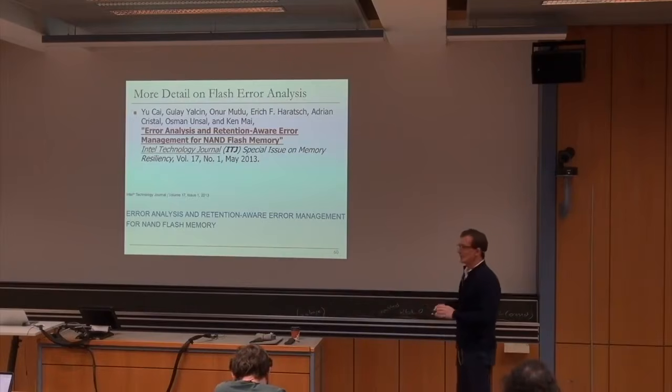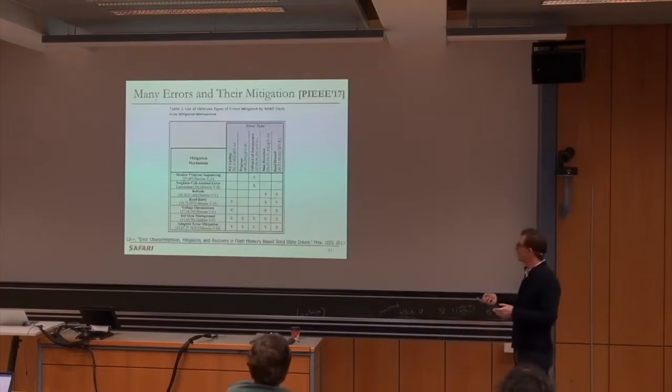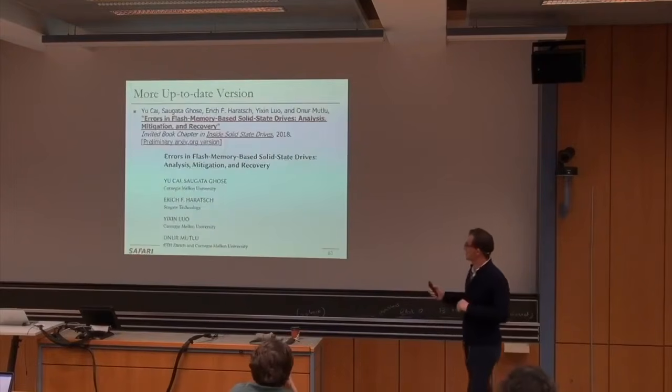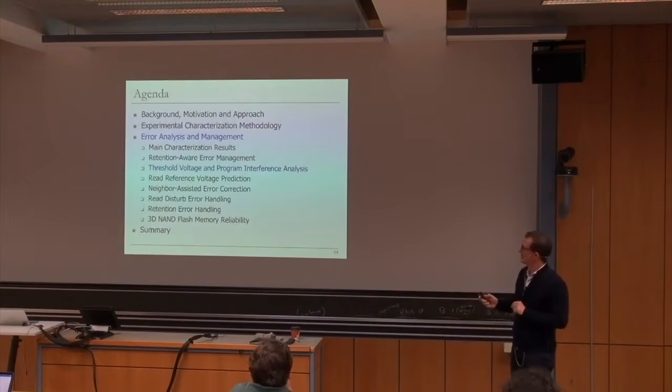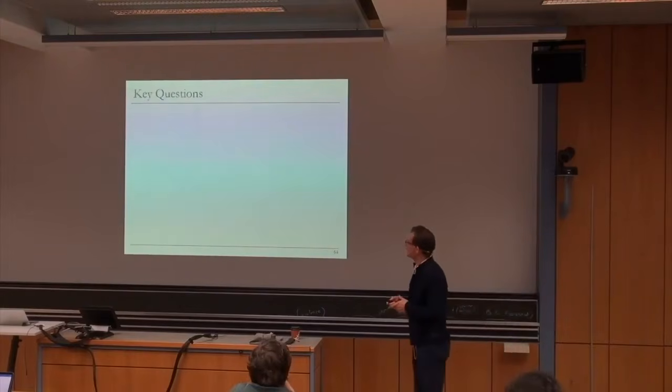Okay, so we've covered the retention errors right now, but as I said, there are many, many other errors. So let me give you an overview of some of these errors. If you're really interested, this paper actually does a lot of justice to these errors. Let's talk about the threshold voltage analysis and program interference.